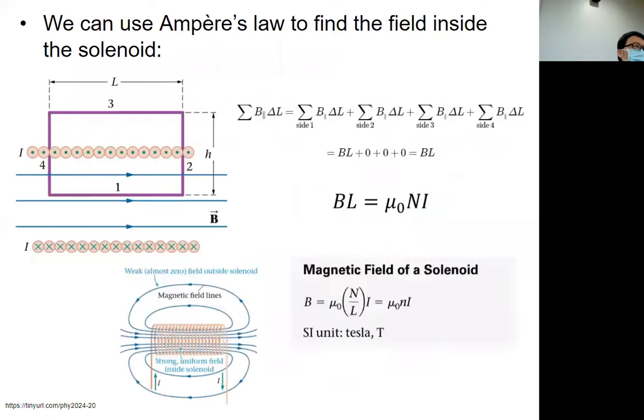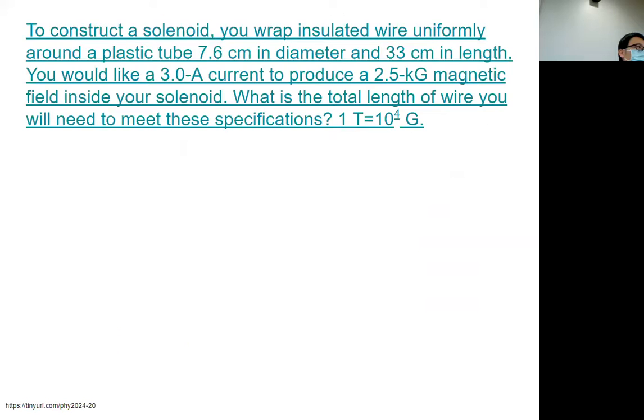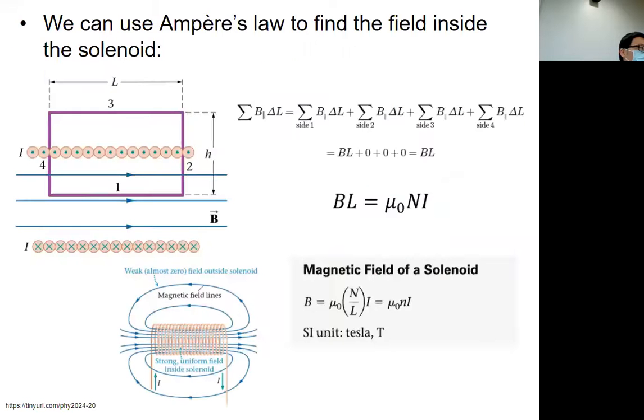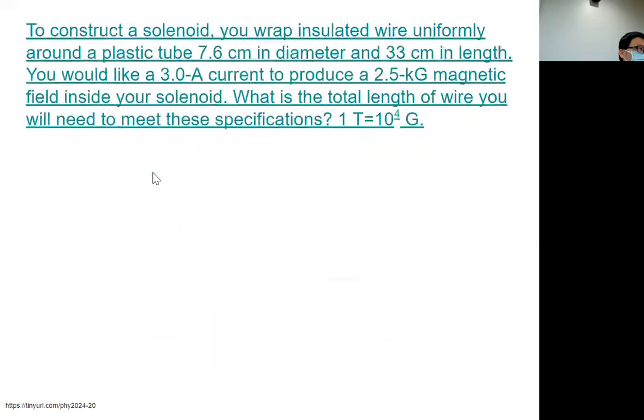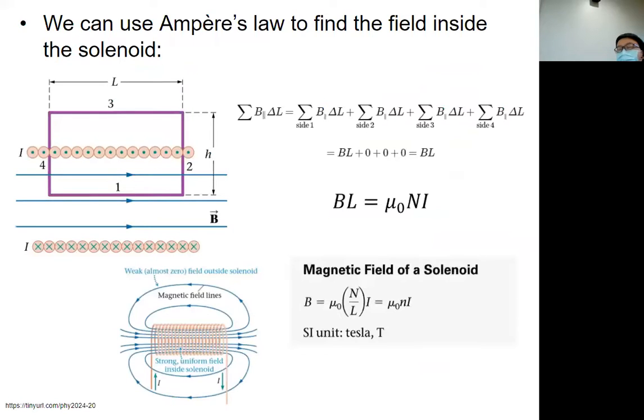For the magnetic field, you can calculate by applying Ampere's law, where you draw a closed path. You can take the rectangle in purple color there for your closed path. Then you can see what current is enclosed in that rectangle. The circles with the dot mean the current is going out of the paper on that part.